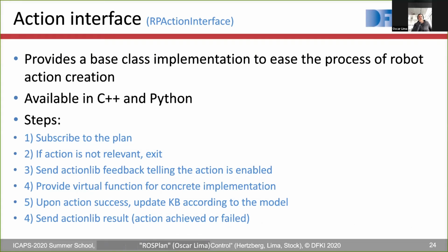So if you are using PDDL, there will be a lot of assumptions that you are making, such that the outcome of executing an action of your robot will always succeed. This is an assumption that PDDL makes, and of course this is not the case in reality. You have stochastic action outcomes, you have events.